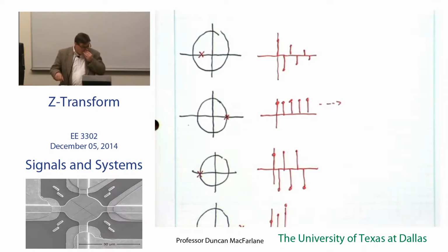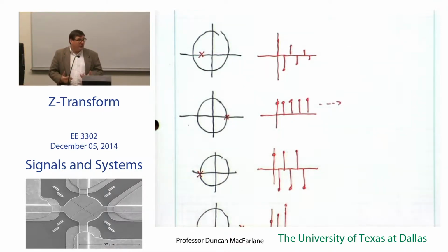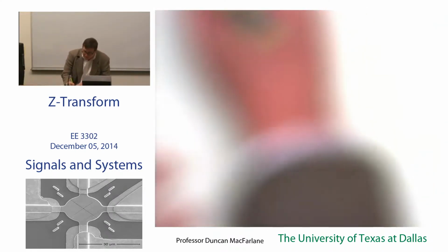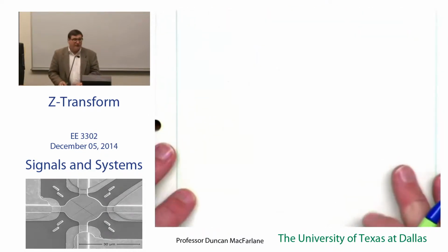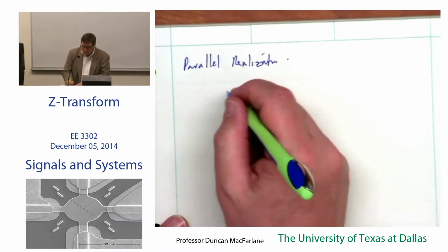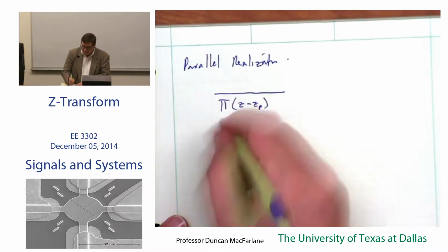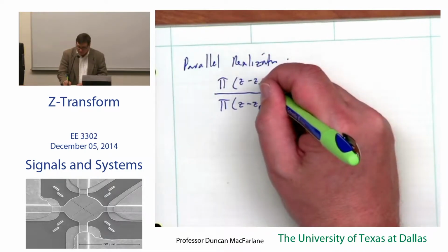All right. So we've seen the direct form realization, which is the polynomials over the polynomials. We've now seen the cascade realization, which is products of the poles and zeros, the factored form. There's another realization, and it's the parallel realization. This starts with a product of poles and a product of zeros.